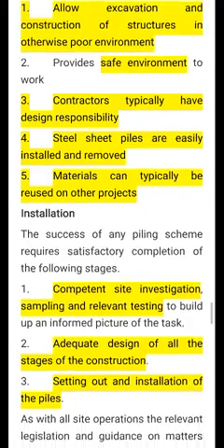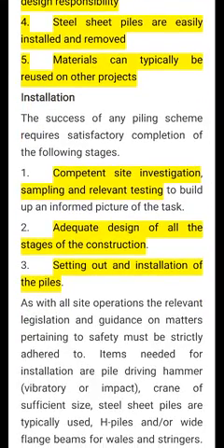Now, how could it be installed? Site investigation, sampling and relevant testing have to be carried out before the construction of cofferdams. If you have the soil information or whatever site information, you can do it very accurately. The adequate design of all the stages of construction has to be planned. Then comes setting out and installation of the piles. That is the installation procedure.